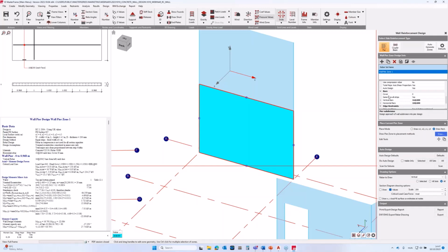Okay, so now we have the same bars in all strips, which might be sensible, but if you do want to use different bars per strip, you can separate the input to specify different arrangements of reinforcement per strip.